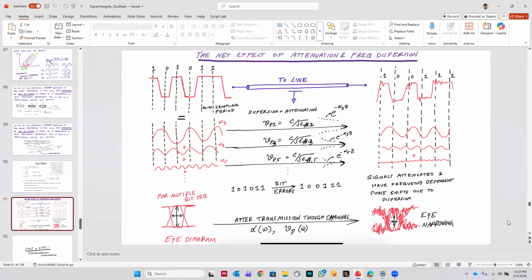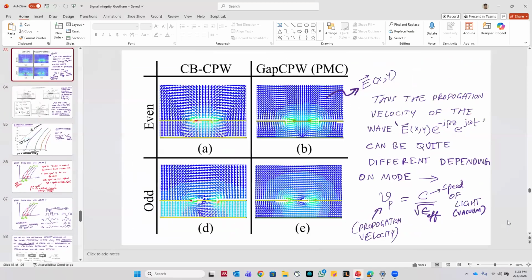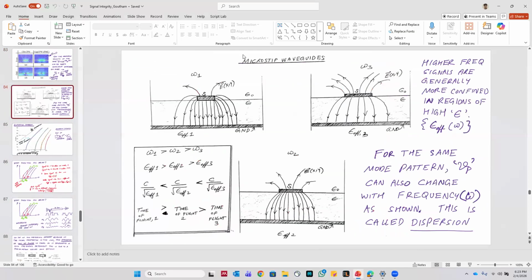Yeah, okay. So one of the first things you need to do is make sure that the substrate's dielectric constant doesn't change with frequency. Second, when you go to higher and higher frequencies, I didn't talk about different kinds of waveguides, but this is a microstrip. So in a microstrip, depending on frequency, the effective dielectric constant actually changes with frequency. But imagine you didn't use a microstrip, but you use a strip line, right? So a strip line looks something like this.